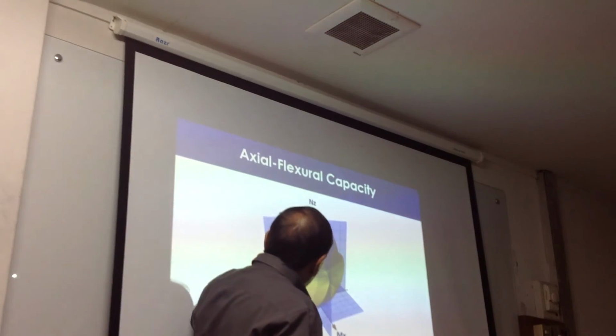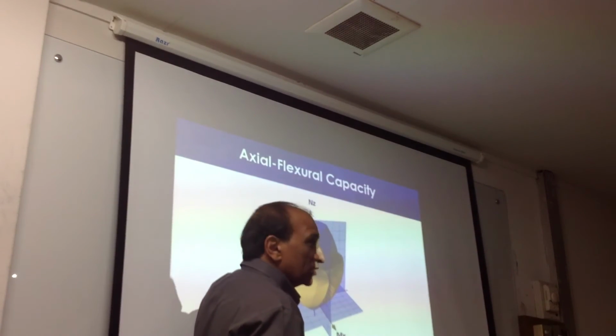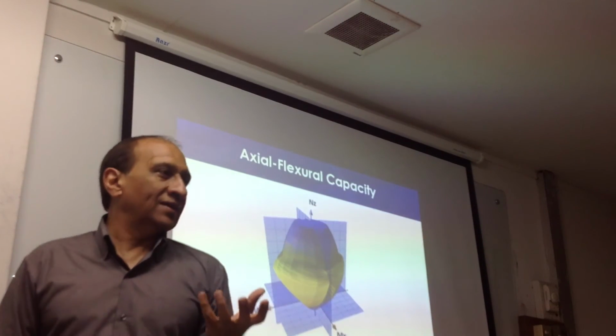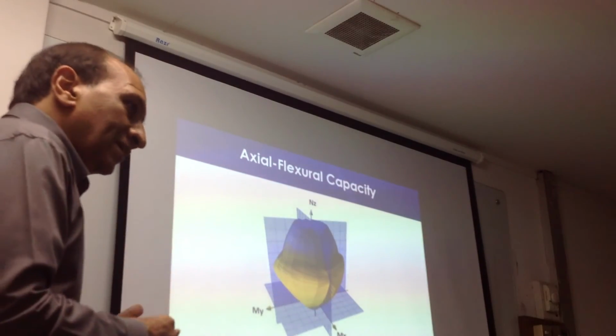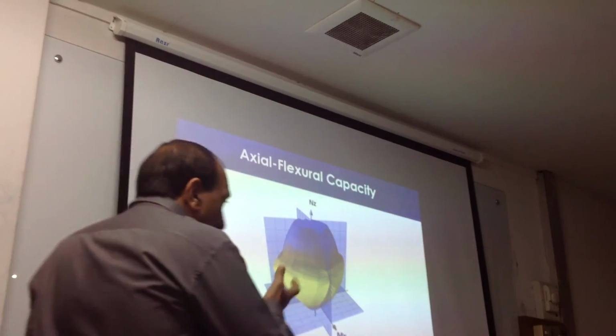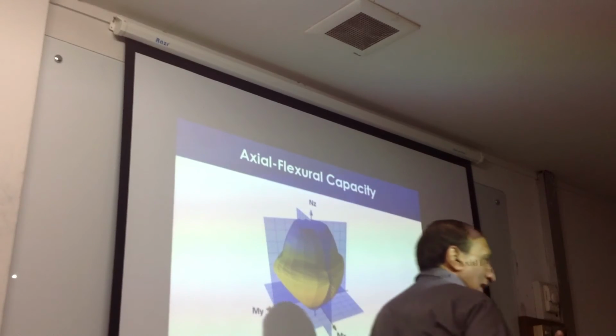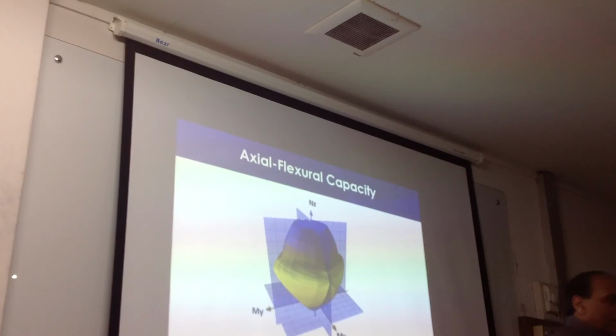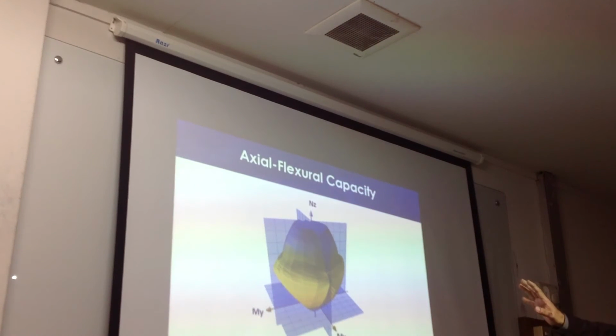And this curve here depends on the four factors. If you remove those factors, this will become different. So everything is embedded in this diagram. The capacity factor will affect this one, the reinforcement location. If you distribute the reinforcement unevenly, this shape will no longer be symmetrical. If the cross-section is perfectly symmetrical, this shape will be symmetrical. If the cross-section is not symmetrical, the shape will not be symmetrical. So this is a property of the cross-section. Once the cross-section is known, the surface is known.